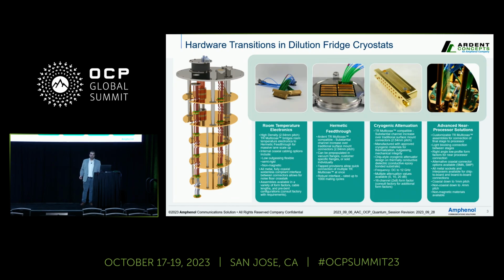Establishing microwave RF connections within the quantum computer relies on specialized hermetic RF feed-throughs. These feed-through components maintain the necessary vacuum levels inside the cryostat chamber while serving as controlled impedance electrical transition points.